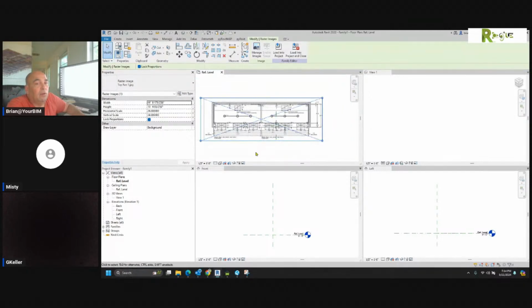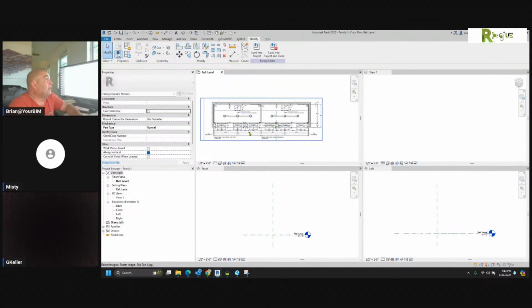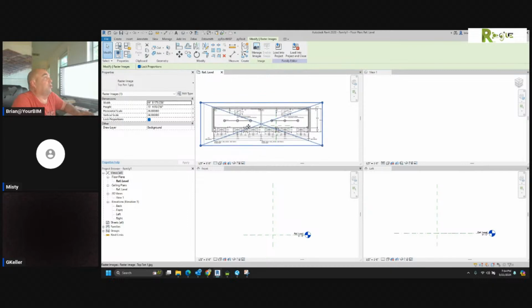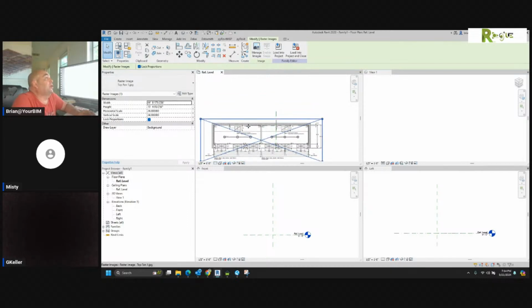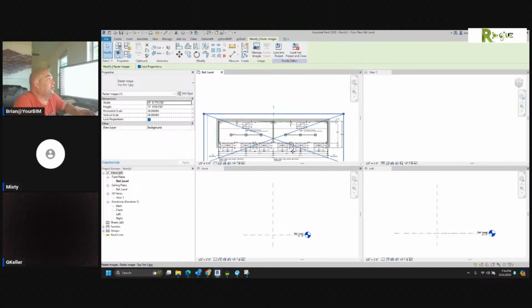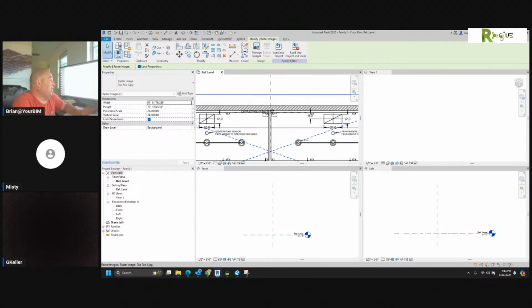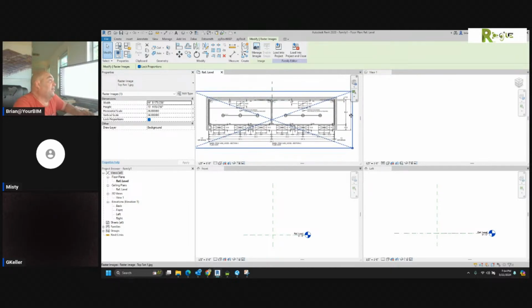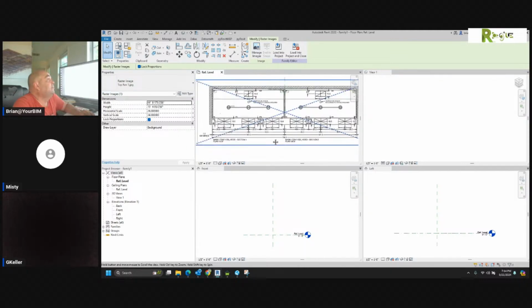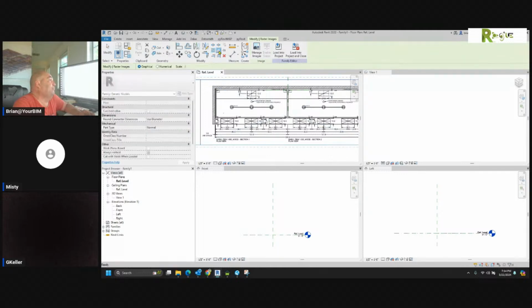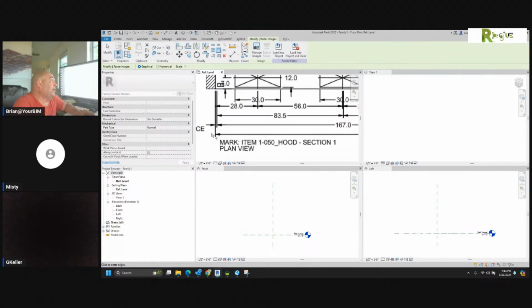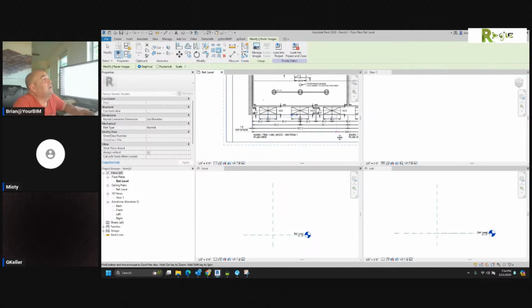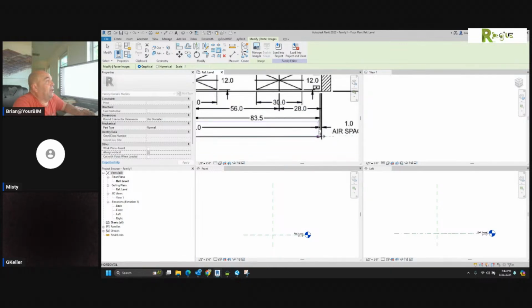Okay, so once it comes in, this is where I was telling you about those green reference planes. What I would personally do is probably line that up against the back of the wall, centered in the 2. We'll get that more accurate in a second, because you don't want to go adjusting that. What we want to do is find the largest number that there's a dimension on. See this 336? We come up here to the scale button. We pick this end of that dimension, and then we pick the other end of that dimension